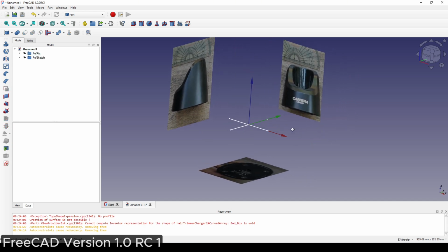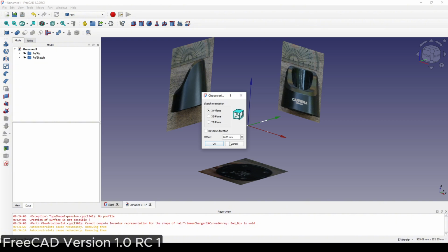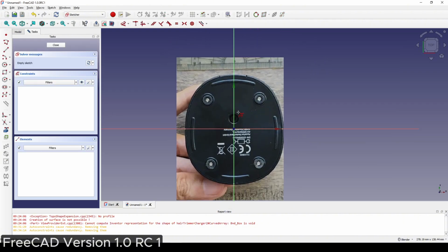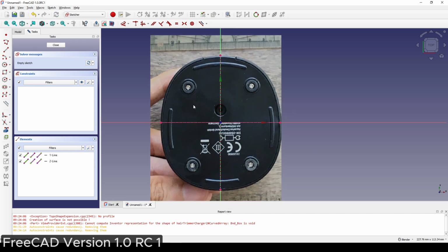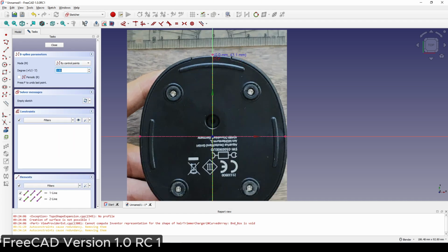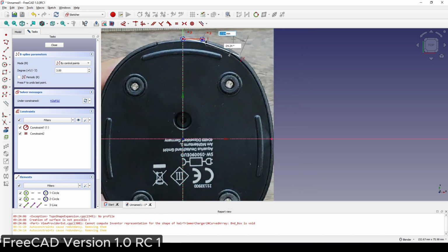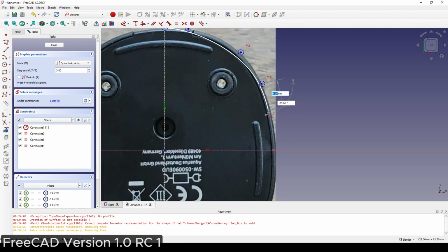Okay. Right, so next I create a new sketch in the top view, and I will reference this line and then this line. I create this spline and start the first point here, second point in here, and let me put 2 points in here, and 1 point, and then the last point in here.